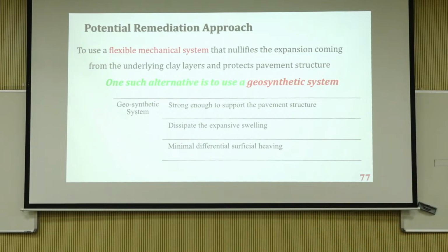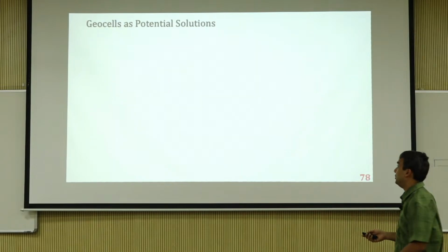So he's like, okay, how do we do that? I said, let's use geocells and geogrids, right? So we're going to fix that. We're going to put the aggregates in there, and rather than studying the problem from top down, now we are flipping the beam problem, where the loading is coming from the bottom and you're just dissipating it. Instead of protecting the subgrade, you are now protecting the asphalt, right? So that's what we did.